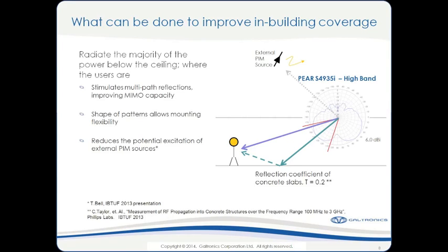Okay. We have time for one more question. As we approach increased deployment of LTE MIMO systems for both DAS and small cells, what crucial attributes of the antennas need to be considered most? I think the biggest concern, and hopefully, if you remember one thing out of today's presentation, is control of where the power is radiated is the most important thing. So if I'm deploying a small cell DAS, I want to control where that power is, particularly for small cells, where each small cell is an independent sector.